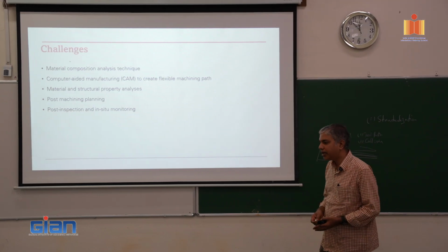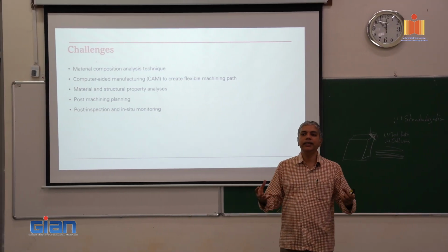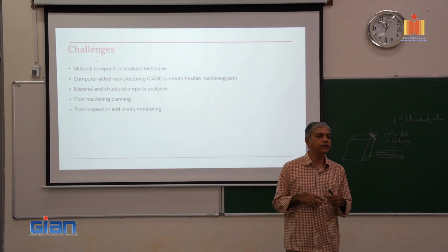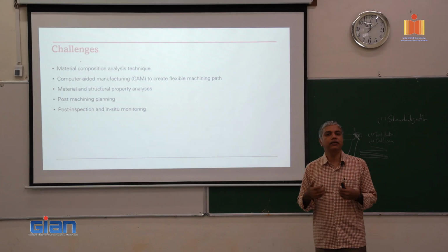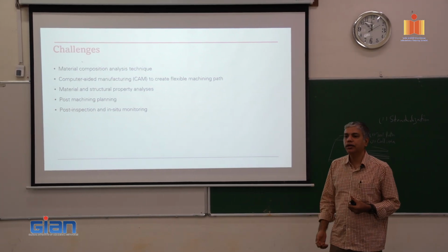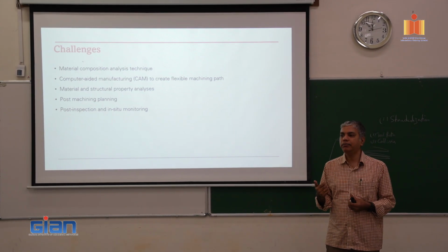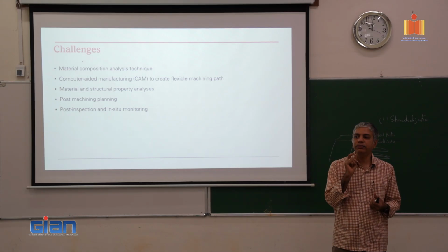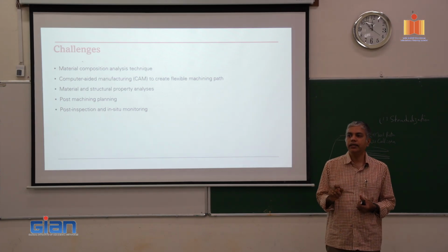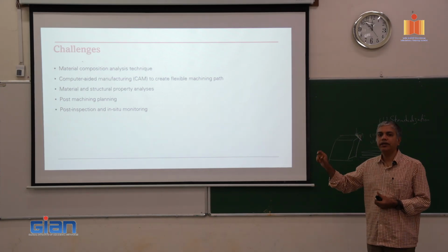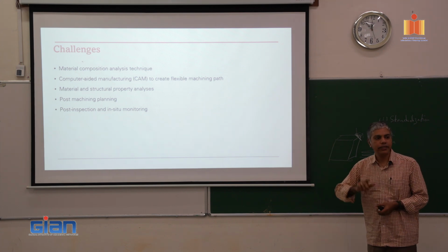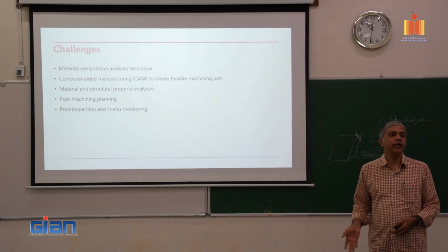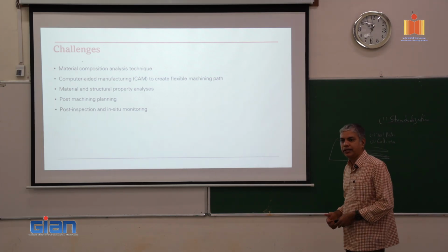And then finally the post inspection and in situ monitoring. Usually what happens is you design the component together with some random points or fixed points to check for integrity, strength, or homogeneity, etc. Here you are not looking at the complete component, you are looking at a specific part of a complete component. So the steps, what to expect, what to look for, again need to be standardized.